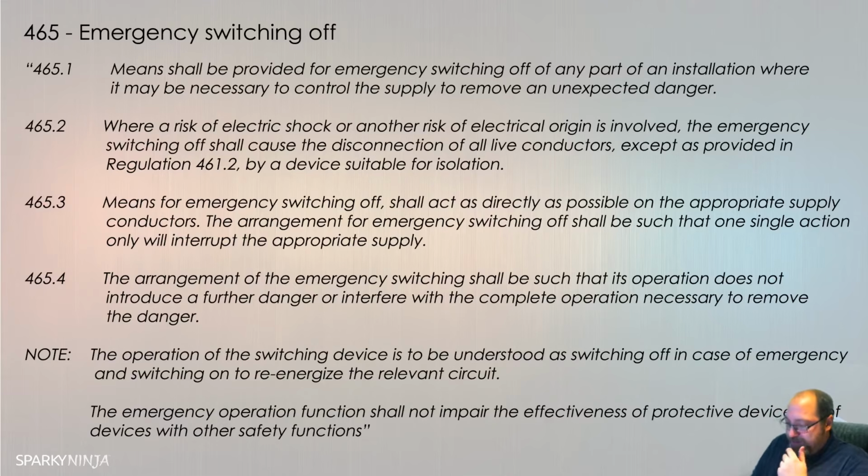And if we go back to the top a little bit, look at circuit breakers. A circuit breaker, the BS EN 60898, can be used as an isolation device. We can lock them off as well, can't we? And it is a single pole device, unless you get a double pole one. We can use it as an emergency switch, which seems impractical, but okay. It's one operation, I guess. And it can be used as functional switching.